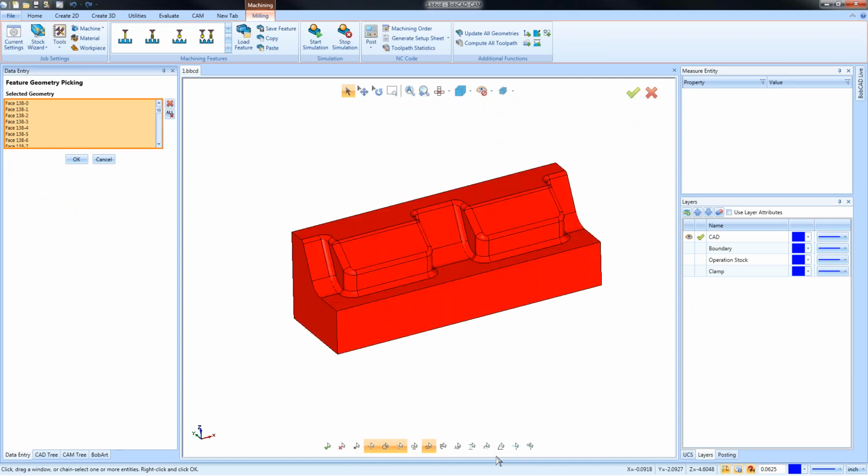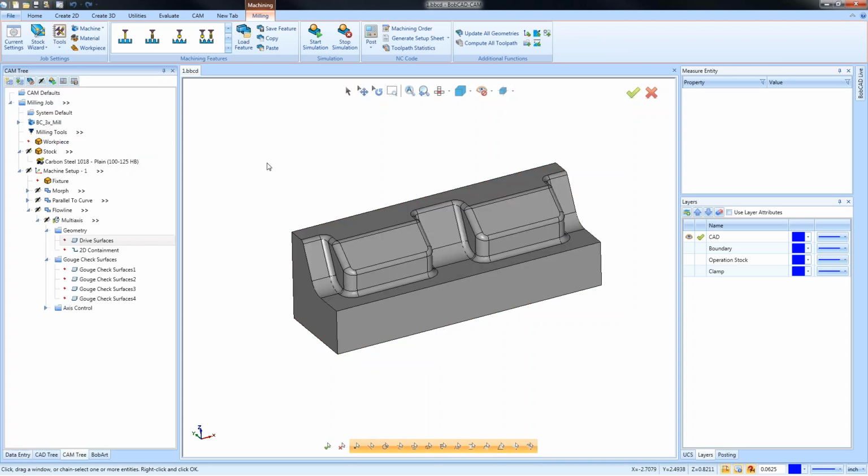There's a number of reasons why, but mainly because these toolpaths have a lot of control and options, and they're best for targeting drive surfaces, okay? And the drive surfaces could be made up of multiple surfaces, but it's unlikely that you're going to try to drive toolpath across all the model. So we're not going to select the whole model, but instead, we're going to be a little more particular about a surface or a series of surfaces we want to work with, right?